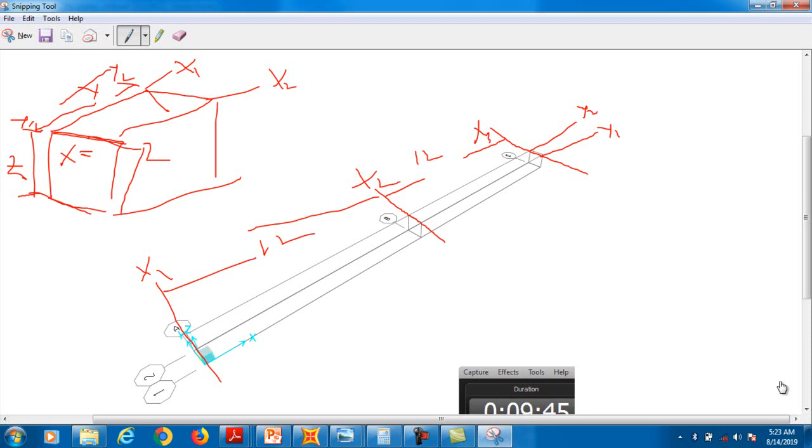So in later stages, once we are analyzing 3D frames, we need this kind of spacing. There I will assume the distance between y1 and y2, and I put that distance, let's say, as 1 feet. Clear? And then we have the other two axes, at this level and at this level, that is your z1, z2. I also assume the distance between them, because I don't need the depth of the column or the depth of the beam. I just assume that, let's say, it is 1 feet.